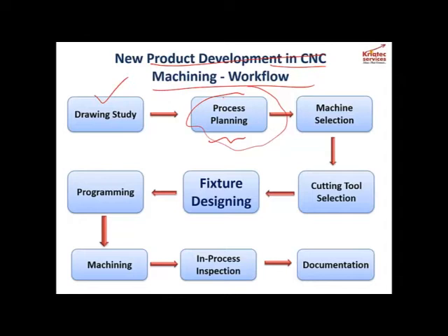And whether I'm going to do it in a single setup or multiple setups plays a major role, whether it can be done in a turning center, whether it can be done in a turn mill, what is the machine, or maybe an HMC, horizontal machining center, or a vertical machining center. That is very, very important.